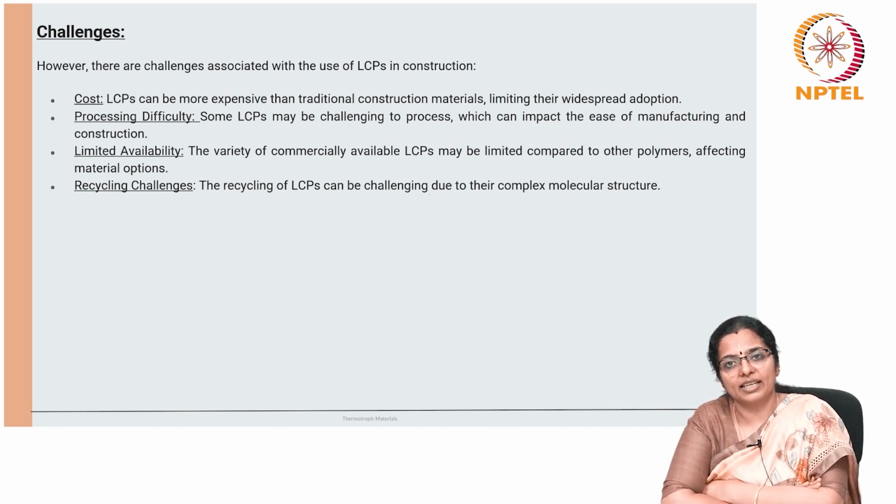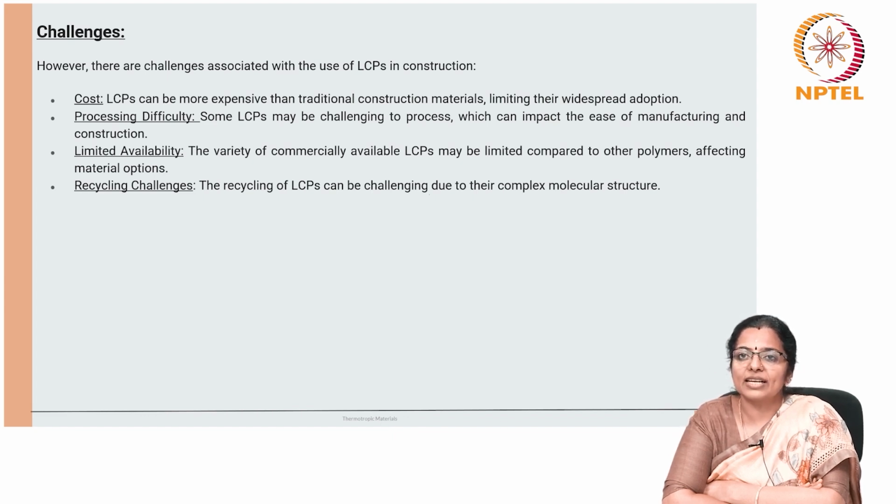If we look at smart glass, then smart glass, which is also known as switchable glass or dynamic glass, is a type of glass that can change its light transmission properties in response to external stimuli, typically electrical voltage or heat or light. And the most common types of smart glass include thermotropic glass, many times electrochromic, photochromic, thermochromic and liquid crystal based systems.